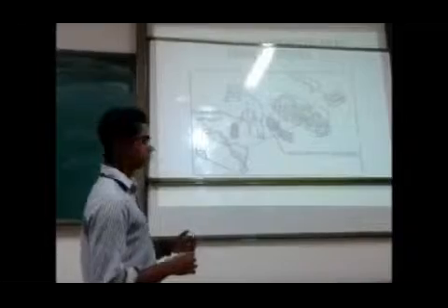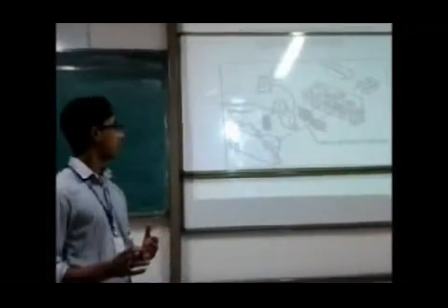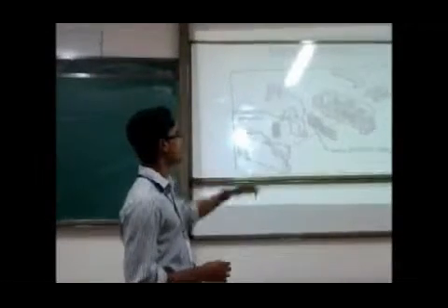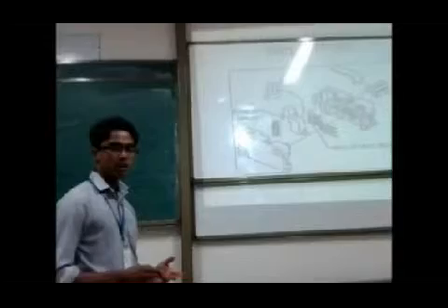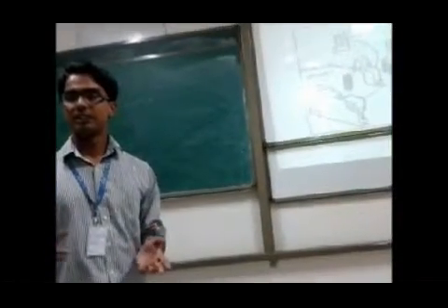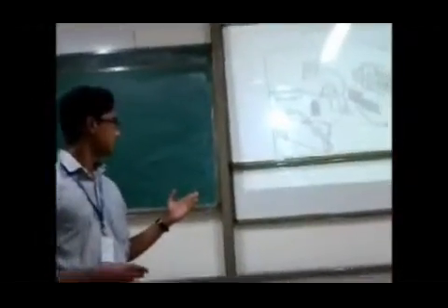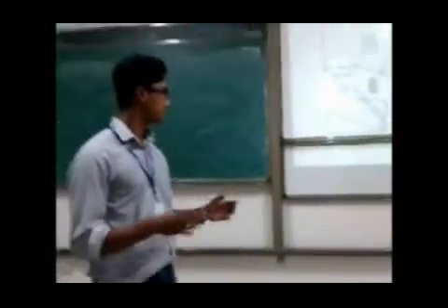So in order to turn on the sensor, we should reverse polarity. Actually, the south pole should come near the sensor, then only it will be turned on. Also in the reverse direction, a normally on switch will result from the reversing of the magnetic field. So the south pole is normally opposite to the digital output of our sensor, maintaining the switch in a normal on state. When the plunger is depressed, the north pole comes near the sensor, turning it off. So that's how it works. In many applications it is used as a switch. That's the main purpose of using it.